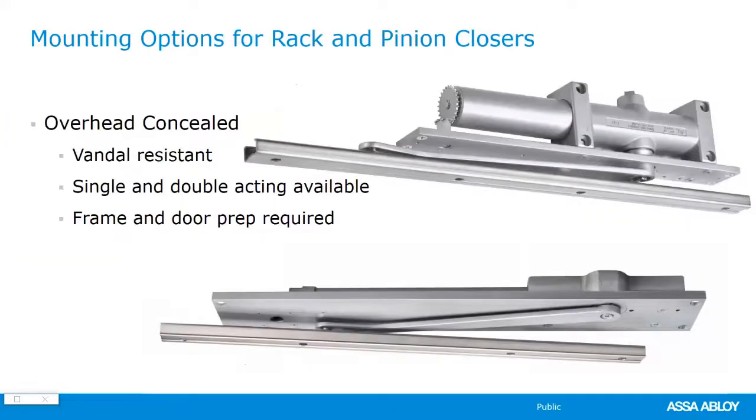You can also get overhead concealed closers from different brands, from Rixson, from Norton. Sargent sells them. Things you have to consider: the frame and the door need to be prepped. I would highly recommend that they're factory prepped. You may have a really good metal shop, if you're a distributor, that's great, but it takes a lot of labor, a lot of time for these types of closers.